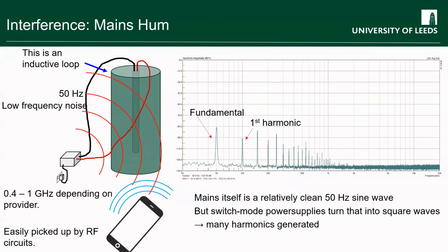Then on top of that, there are extrinsic sources of noise that arise from how we set up our experimental environment. I already discussed some of this when we talked about cabling in the first of these sets of lectures. We talked about inductive pickup, so mains pickup, which is what happens when you have a big loop of cables, where your plus and minus cables for doing a measurement are widely separated.